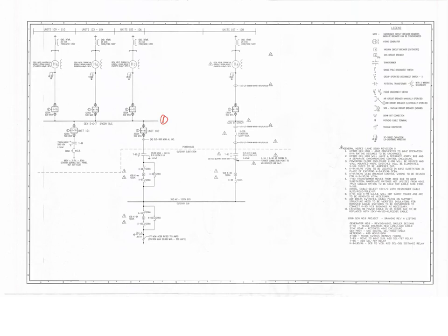I would say this is bus 1, right? Because you can see you have a transformer here. This is bus 2. So on both sides of the transformer, I have a bus. I don't bother putting one in the cable, although if you were in the real world and you were using a program like Aspen, this cable right here actually has an impedance associated with it. And because there is an impedance associated with it, you actually have to have the element in there, right? So the transformer and the cable would look like that.